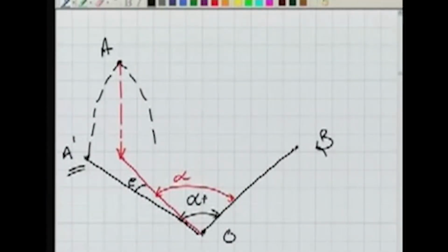So earlier the cone was being formed in that direction; now the cone will be formed in this direction. If in this case I bisect A and bring it down, it will come here, and then I measure my angle.